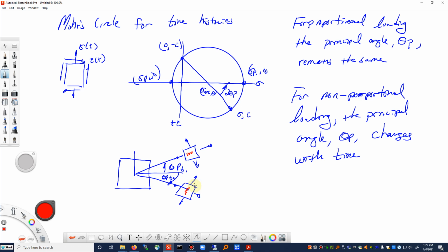All right, so I wanted to give a little bit of background on what we mean by multiaxial fatigue and multiaxial stressing. So there are a couple ways that people have tried to handle this situation. Some of them work for proportional loading only, and some of them work for proportional loading most of the time. And we're going to talk about those. And then later on, we're going to talk about something called a critical plane approach to multiaxial fatigue, which is a little more physically based and seems like the most sound of several methods.